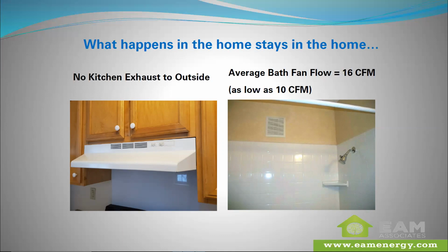And so I like to use maybe like a 20-minute delayed off in a lot of our projects, unless they, aside from using an occupancy sensor, which also works well, but if you're just doing an on-off switch, we do like a 20-minute delayed off timer.